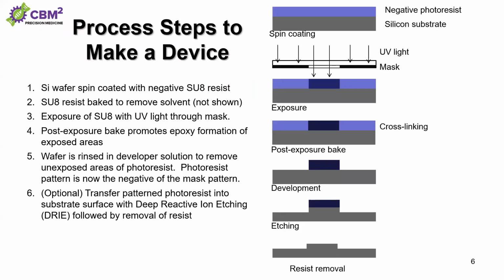Okay, so this is the actual process for photolithography. The first step is normally to spin coat the resist layer on the substrate. For most cases, people use silicon as the substrate, but you don't have to use it. For making microchips, they mostly use a silicon substrate. Then you put your substrate into your mask aligner, put the mask at a certain location using the aligner, and then you shine light.